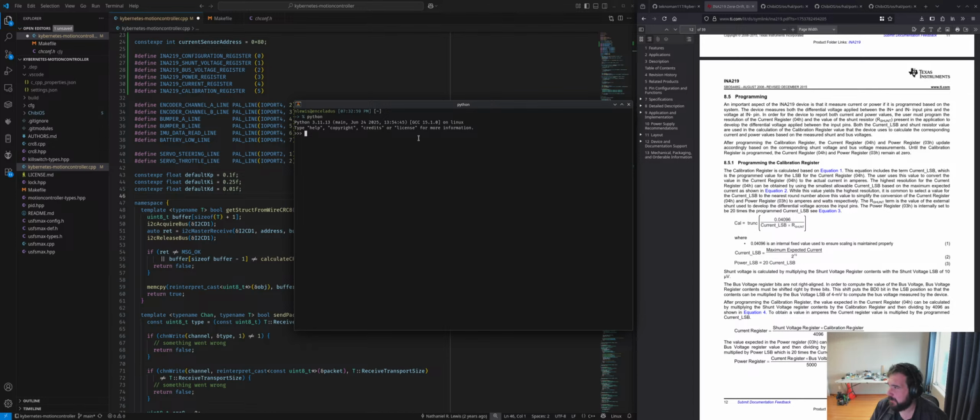The Raspberry Pi 5 that we'll eventually use can draw 15 watts. The camera can draw 15 watts. The GPS probably draws a few watts. And there's really no other logic devices, so we're going to say that 7 amps realistically is the maximum that we want to be able to measure. So we'll say 7 amps.